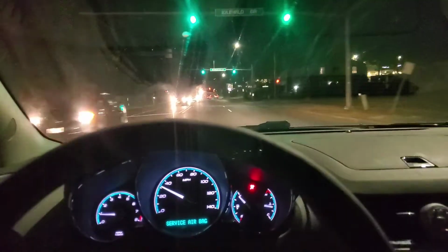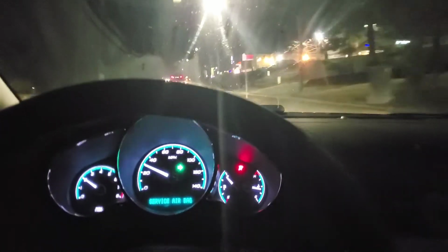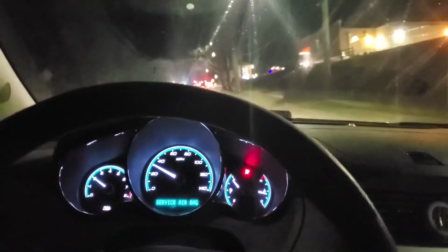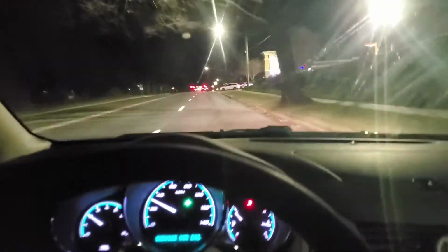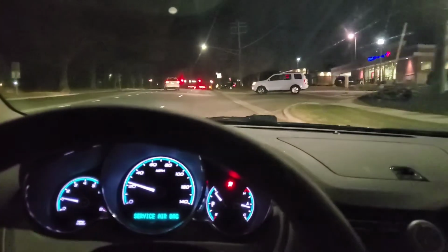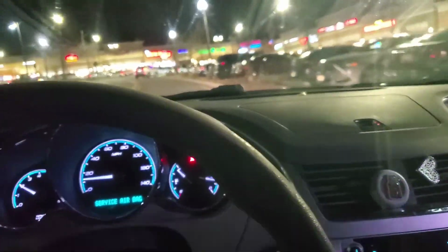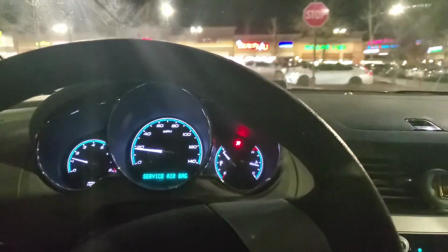All right, so I'm at 1% now, and my hand's not on the steering wheel. It's driving straight. Just left my buddy's house, used his Autel. He told me what number it was, but I forget now. And it was really simple. You just hit calibrate and it says in progress, and then complete and done. So I did the steering angle sensor, the torque input sensor, and then the tuning. And now the effort is even left to right. So I'm at 1% here.